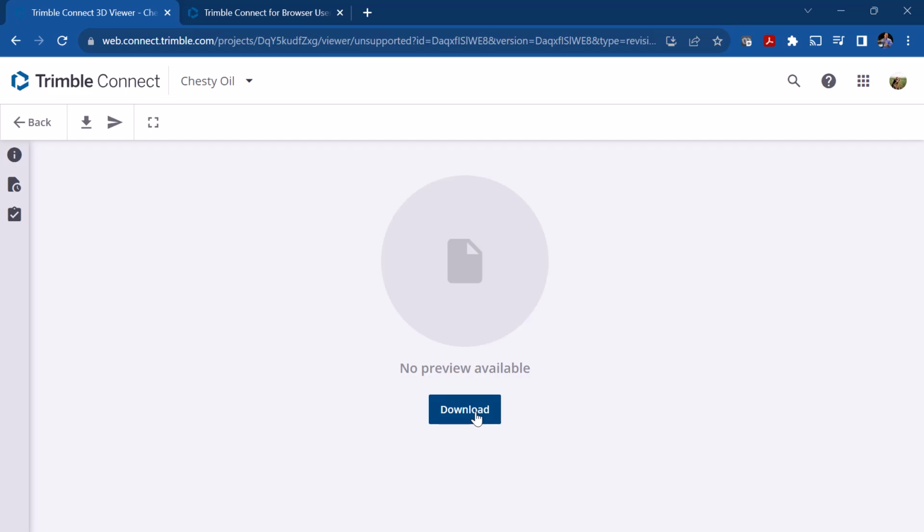So if you were using Trimble SiteWorks and you had connectivity in the field, you could use the web browser on your tablet, on your TSC7, download these files, load them into your SiteWorks project, and you'd be able to stake it out. So that's one way to remotely send data to the field if you don't have our WorksManager product, which would also connect with Trimble Business Center and send data to the field. So this is just an alternative method of sending data from Business Center to Connect to a device.